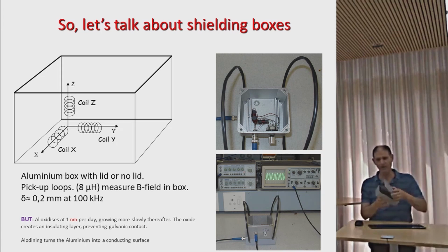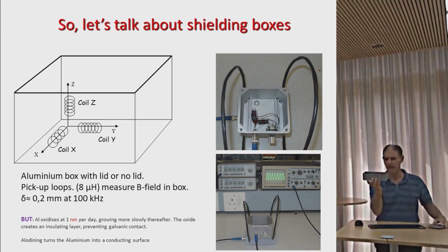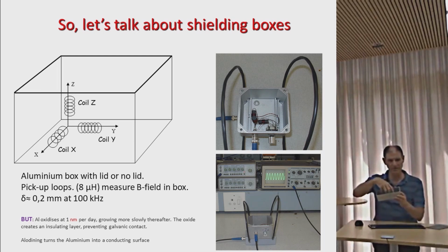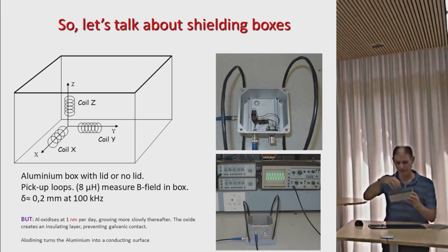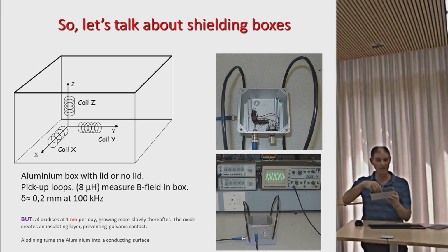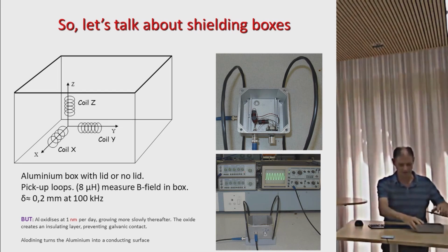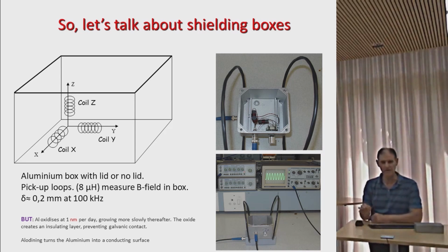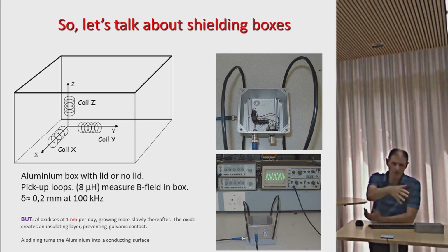And that's because oxide's beginning to grow. And currents, like water, will always get in through gaps. The currents get in through the gaps, excite fields in the box, and this causes coupling to the inside of the box, which is electromagnetic susceptibility, or comes out of the box, which is electromagnetic interference. The experiment which is implied here is a fun experiment to do, and most people after doing the experiment find that they understand how these currents and fields cause penetration into a box or out of a box.